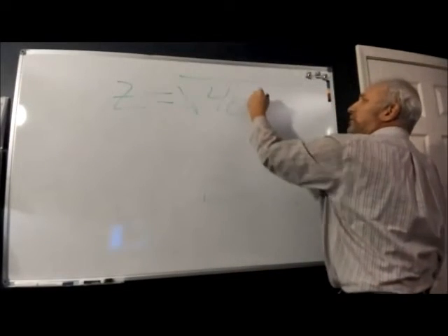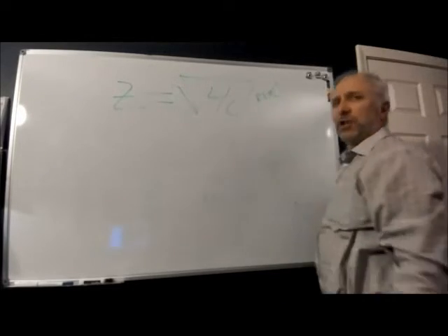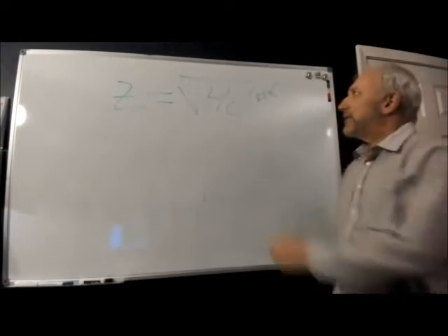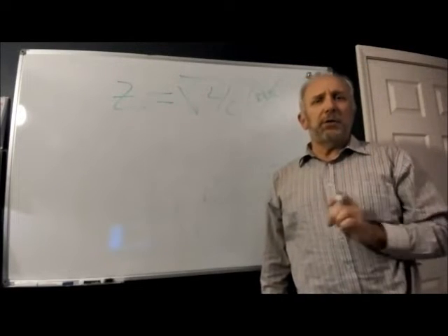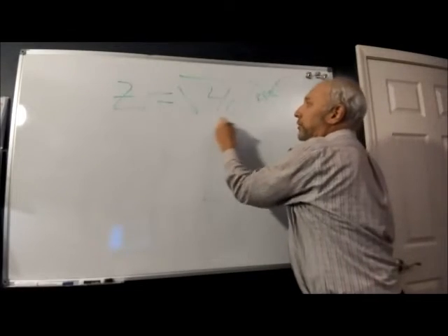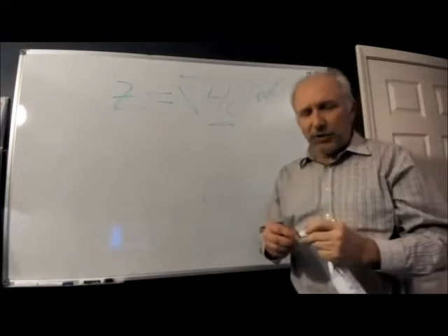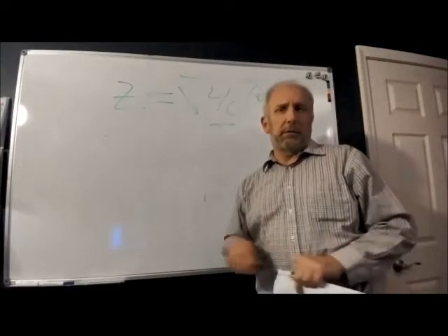And actually, there are some real terms out here, some resistance and conductance. You know what? That stuff really doesn't matter. The impedance of the transmission line is governed by the square root of L over C. What L and what C are we talking about? Are we talking about the lumped L, or are we talking about the distributed L? Distributed L. It's Henrys per meter divided by Farads per meter.